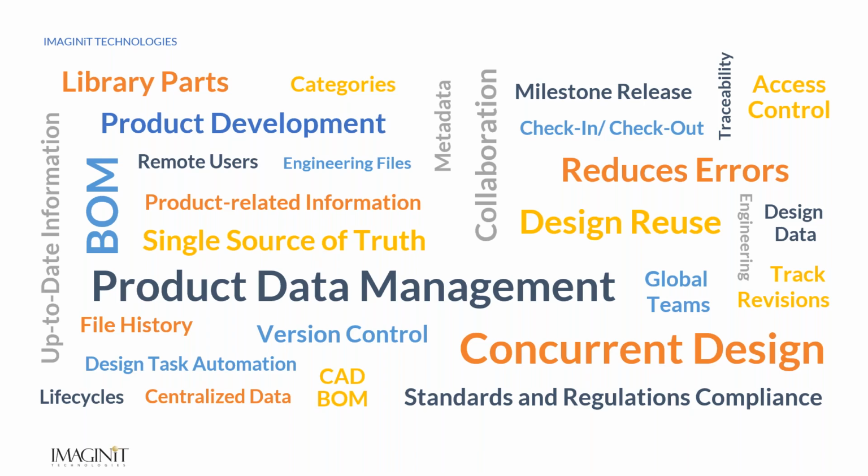At the heart of this is product data management, or PDM systems, if you will, like Vault. And this provides things like single sources of truth that helps you reduce errors in your data integrity, allows you to track the check-in and check-out and create audit trails for who did what, when they did it, and why they did it. It also can lead into standards and regulations and access control, like if you have ITAR considerations and you need to prevent certain people from seeing certain areas. These are all things you can perform with a healthy Vault system.